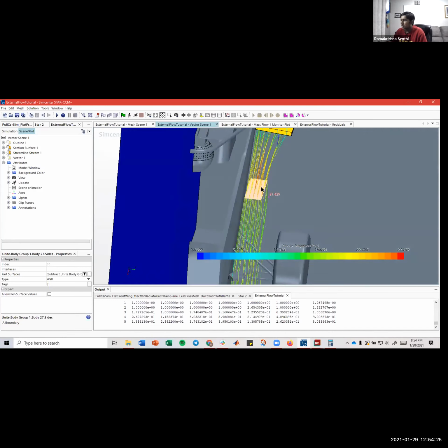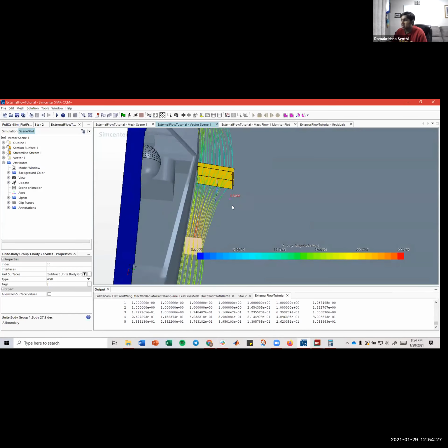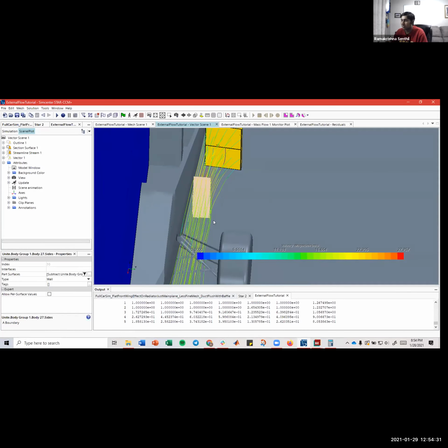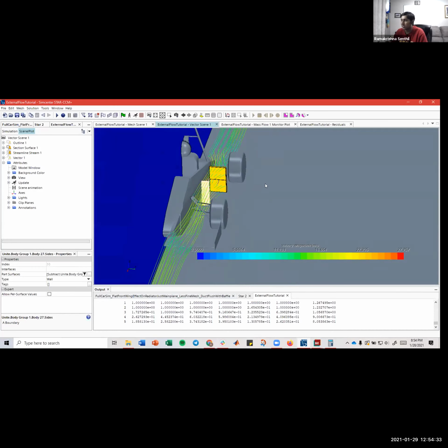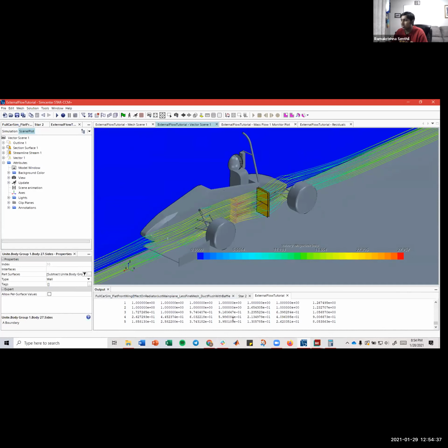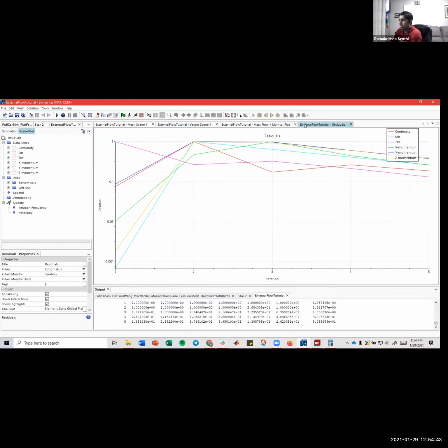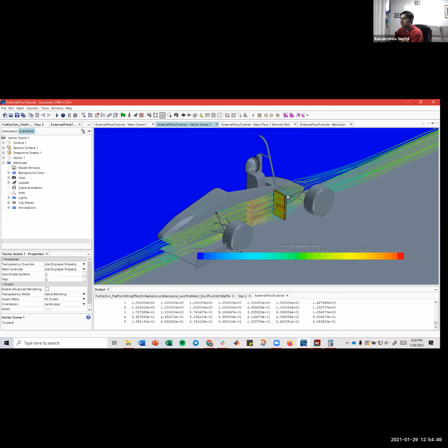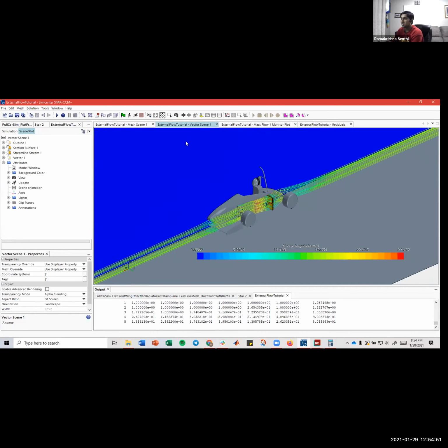At first glance, it looks like there's no flow separation at all. It pretty much follows the spline exactly. But we've only run the simulation for 5 iterations. Usually we'll want to run it for a minimum of 1,000 iterations, and we want these residuals to get a lot lower than where they are. Yeah. So that is an external flow simulation.